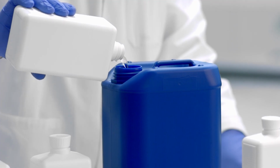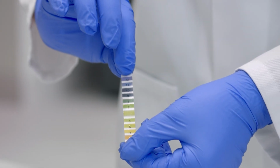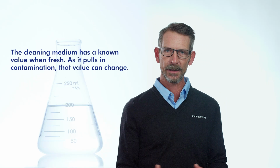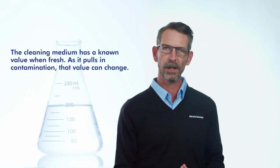pH, again, very similar to the other two, however, it is obviously a different function. So on the pH, depending on what type of cleaning medium or solvent you're using, you may have an acidic or an alkaline pH. When we're looking at the pH, 7 would be neutral, and you can go above or below. So again, the cleaning medium in its fresh state is going to have a known pH value. As the contamination is absorbed or pulled into that cleaning medium, it could impact that pH. So another test that we recommend to ensure that your cleaning medium is efficient and effective is also pH. And all of those functions are related to product reliability.